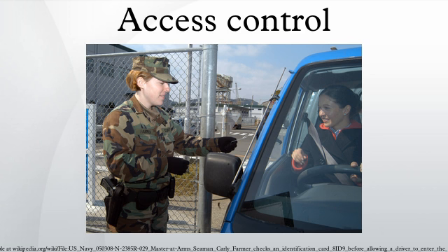Generally only entry is controlled, and exit is uncontrolled. In cases where exit is also controlled, a second reader is used on the opposite side of the door. In cases where exit is not controlled, free exit, a device called a request to exit is used. Request to exit devices can be a push button or a motion detector. When the button is pushed, or the motion detector detects motion at the door, alarm is temporarily ignored while the